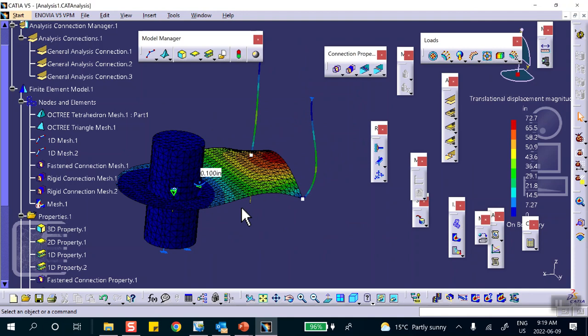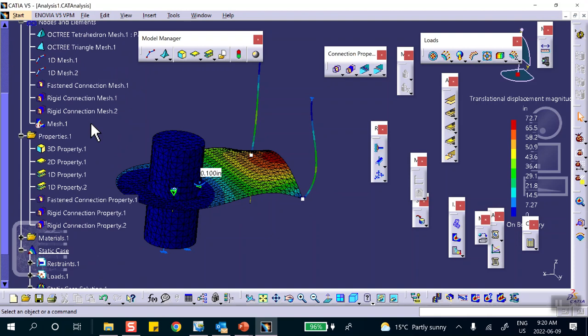Because remember, when you put a pressure, it can be going like that, or it can be going like that. Okay? For us, the way to fix it, just reverse the sign. There is a system behind it. It's not random. We don't worry about it. If it goes in the wrong direction, that 100 psi that I put there, make it negative 100 psi, and hopefully that will give you something that you like. So let's go to the pressure that I put in there.